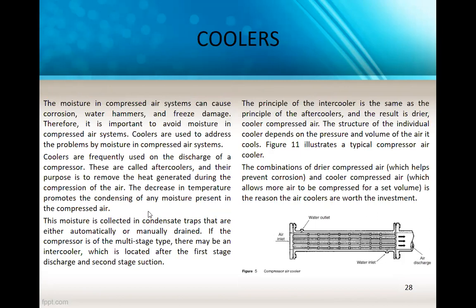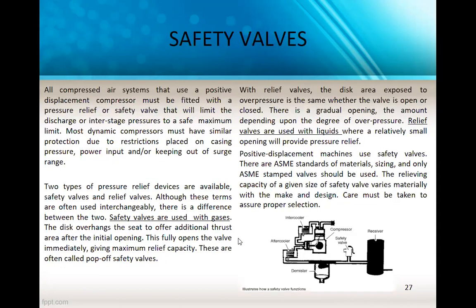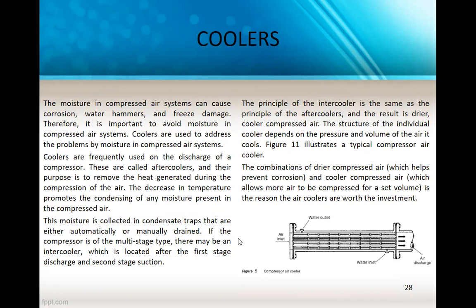So, coolers and aftercoolers. We mentioned aftercoolers, and also intercoolers. The moisture in a compressed air system can cause corrosion, water hammer, and pressure damage. Therefore, it is important to avoid moisture in compressed air systems. Coolers are used to address the problems caused by moisture in compressed air.